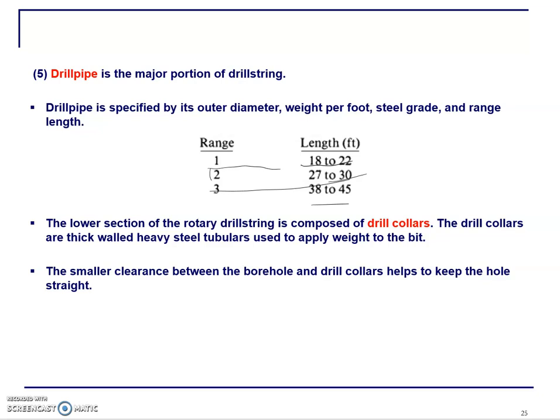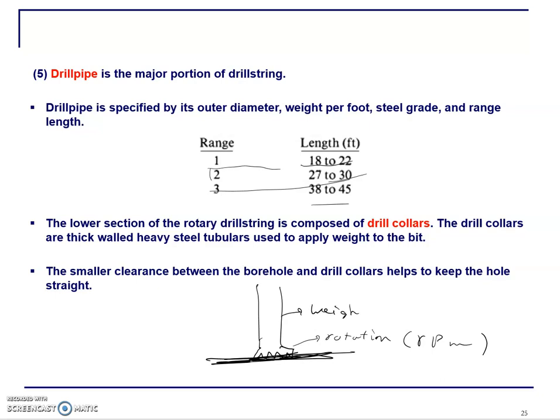what causes the drilling to happen is 2 things. One is the rotation of, so let's say here is the level that we are drilling at, the surface, the bottom of the wellbore, and here is your drill bit, right? 2 factors play a really important part. One is the rotation of this drill bit, which provides RPM, and another factor is weight on bit.